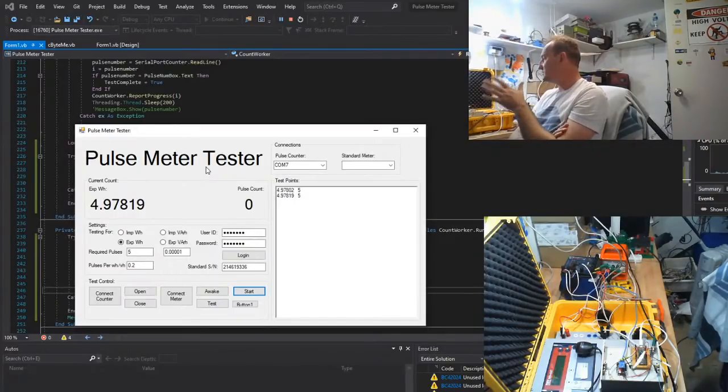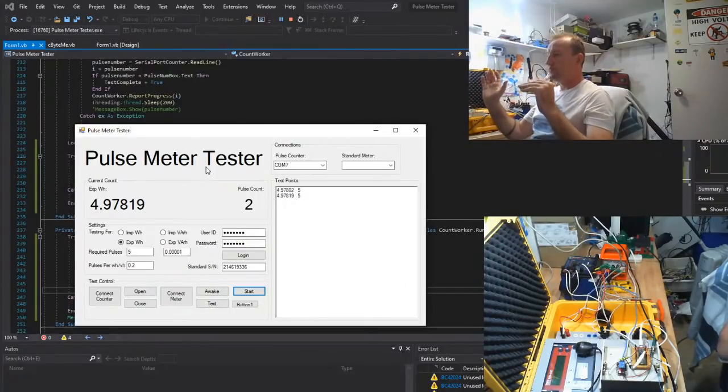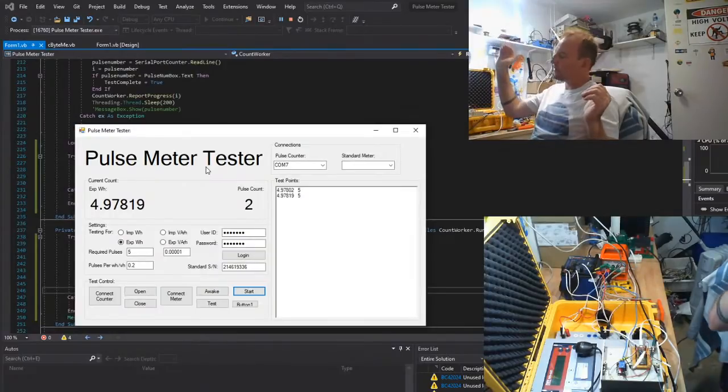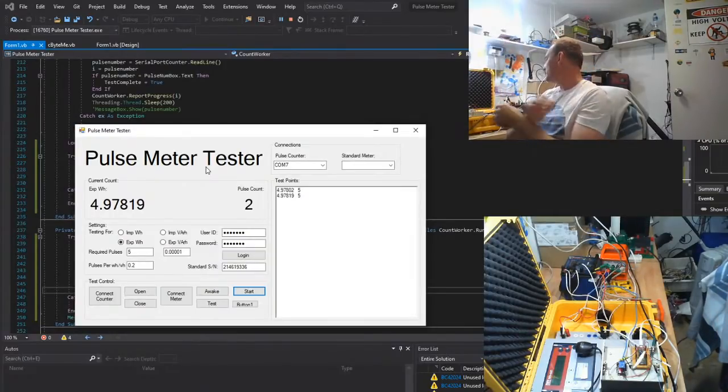Yeah, so the whole idea when you calibrate meters is you've got to change the phase angle and have different current loads. So the meter is working within its range, to check that it's working at different points. Because electricity use is not linear, you can't just pick these 3 points at this angle or whatever. You might be importing, you might be exporting. Like if you're a solar customer, you may be running in phase, out of phase.